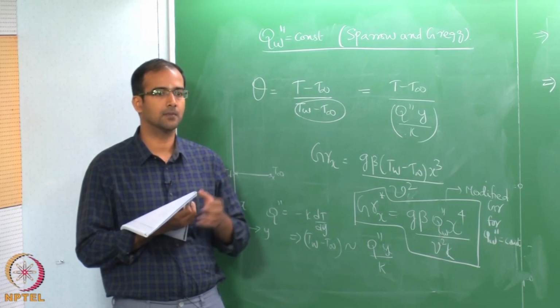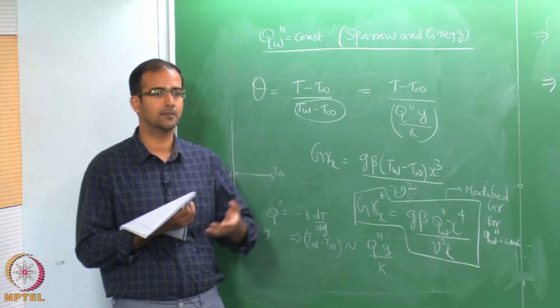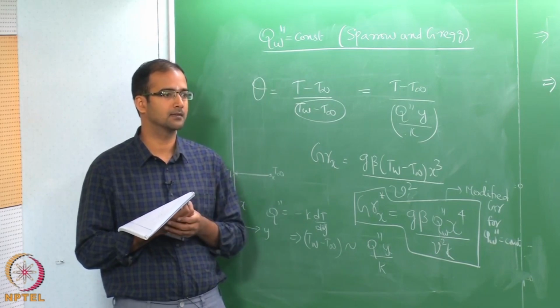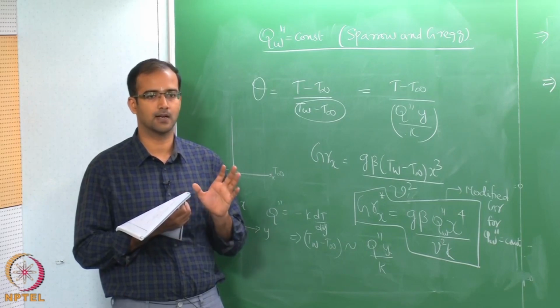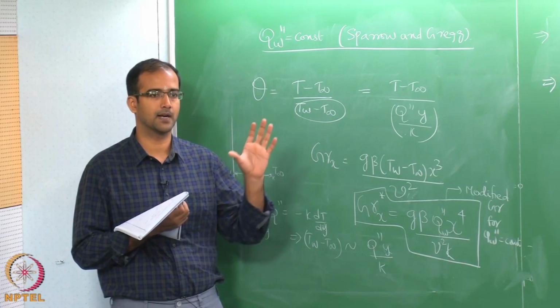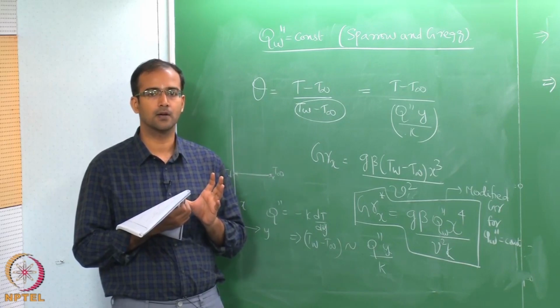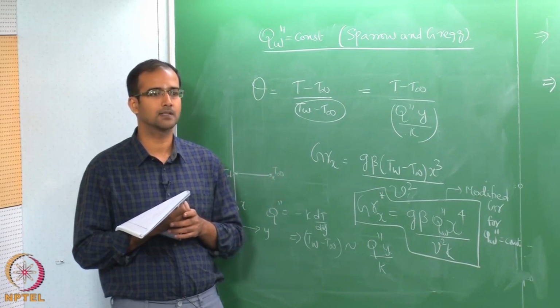The Grashof number is only based on one local coordinate. Why should we use y times x? How do you then compute your graph? Is it a 2-dimensional variable? Grashof number is just a local coordinate which is attached to the plate length. So, we cannot define a 2-dimensional Grashof number here, it is like defining a 2-dimensional Reynolds number.